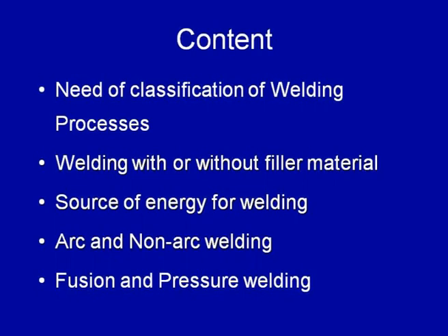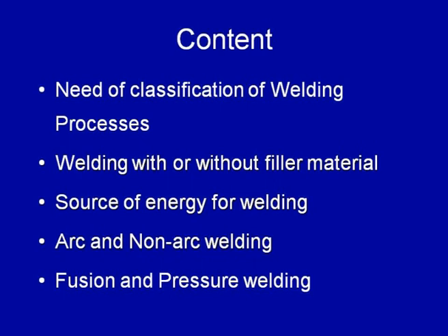The first is the need for classification, and then the bases on which welding processes can be classified: welding with or without filler material, welding using a variety of sources to apply energy, welding based on the arc or without the use of an arc, welding where fusion takes place, or processes where only or mainly pressure is applied to get the weld joint.